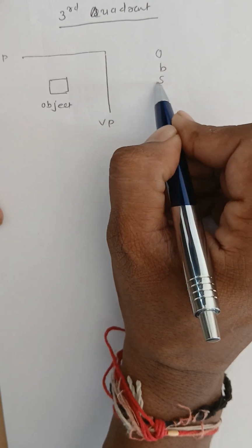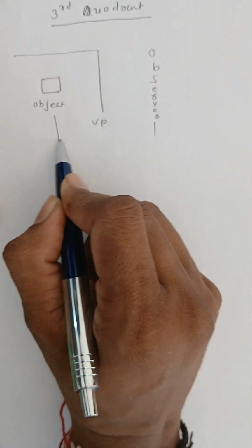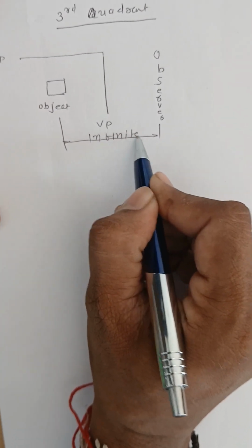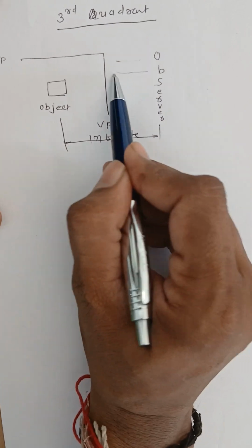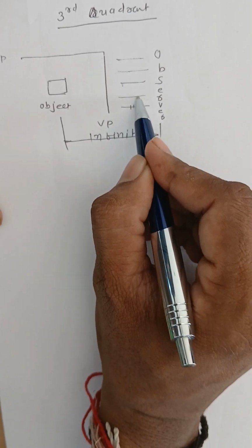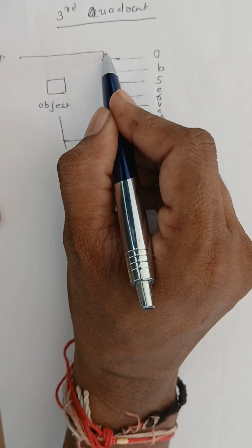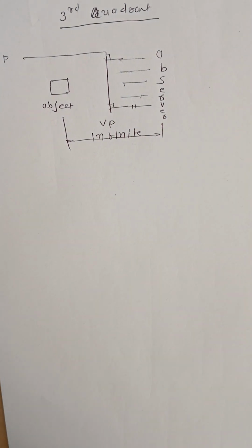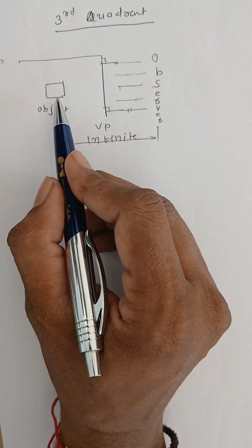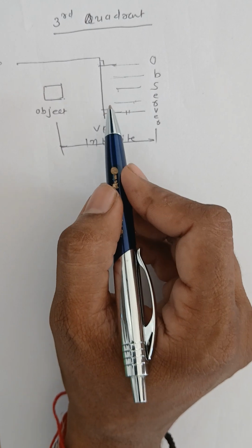Observer will be at infinite distance from the object, right? Rays from the observer or rays from the object are parallel with each other and they are perpendicular to the plane of projection. Hence this is known as orthographic projection, right? Again, are we able to see the object from the position of observer? The answer is no. Why?